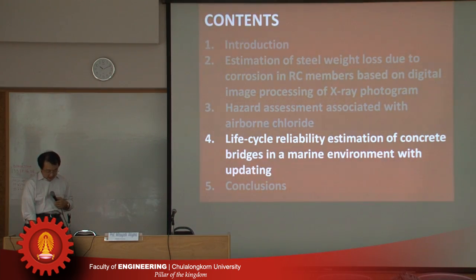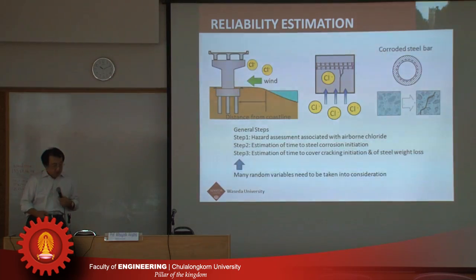So finally, I present life cycle reliability estimation of concrete bridges. To estimate the life cycle reliability of concrete structures, we have to follow these steps, including hazard assessment associated with airborne chloride, as I mentioned, estimation of time to steel corrosion initiation, and estimation of time to cover cracking initiation.